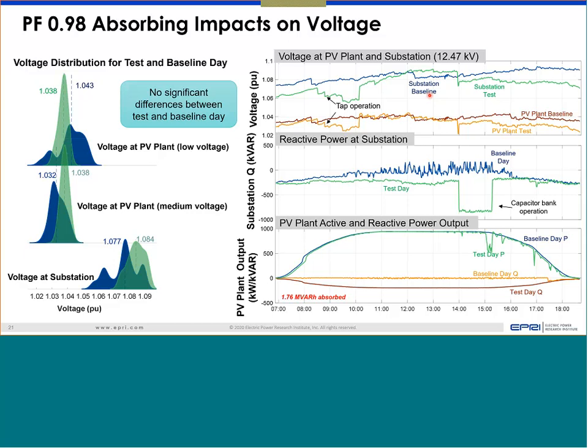Okay. So, single phase outage, if you remember the islanding discussion that we had, resultant of the single phase outage, what the inverter will see at its terminal, whether it will see an outage or three good voltages within the operating range, that will dictate. So if the inverter sees the outage or a protection relay picks up that open phase, of course it should disconnect.